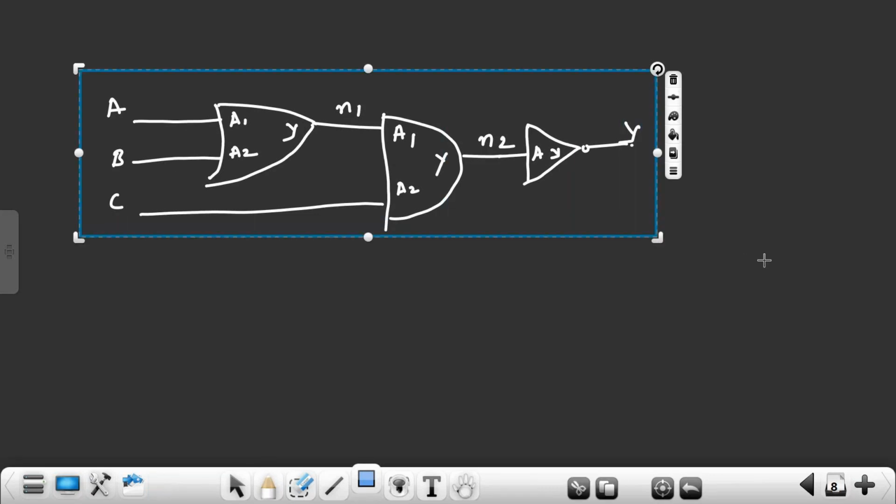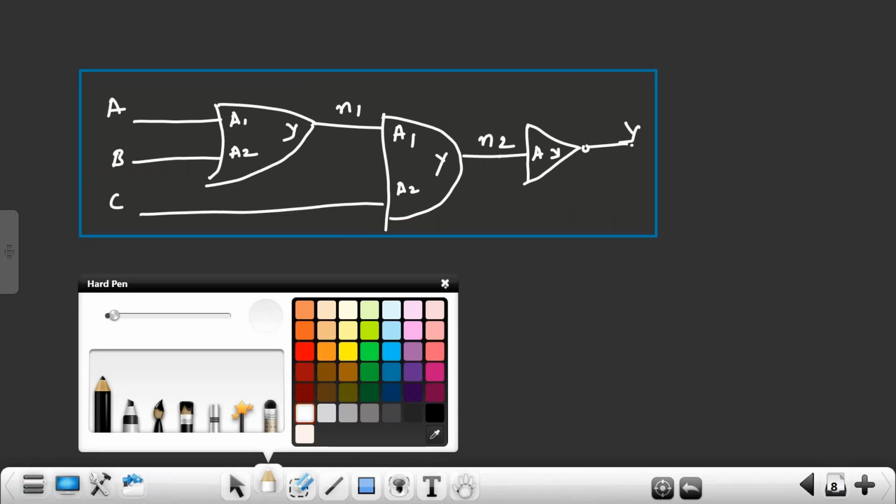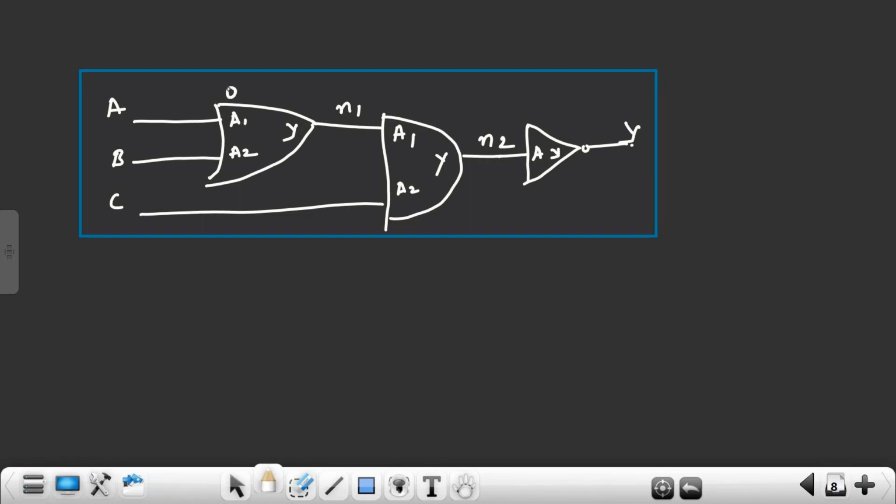What we got after synthesis, right? And this is an OR gate. The OR gate name in the Liberty file is OR2. OR2 means two input OR gate. The AND gate name in the Liberty file is AND2. The inverter name in the Liberty file is INV, just INV. The Liberty file has different things again. It has different drive strength and different threshold voltage cells. So that we'll discuss later. But now the name of the OR gate is OR2, the name of the AND gate is AND2, and the name of the inverter is INV.